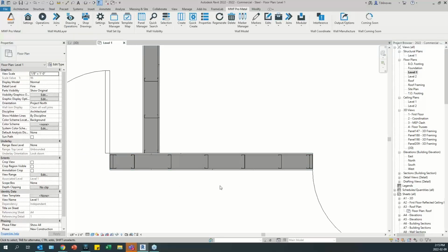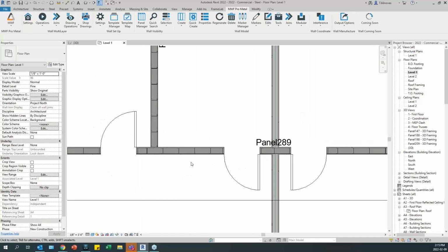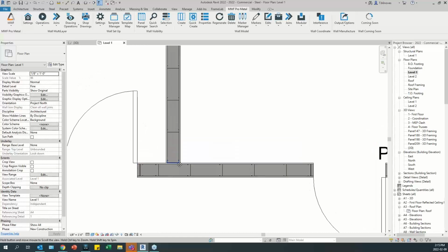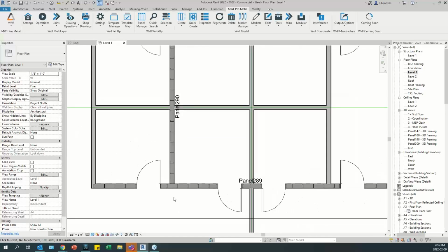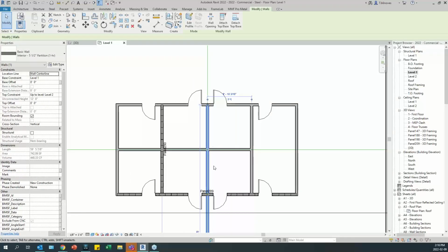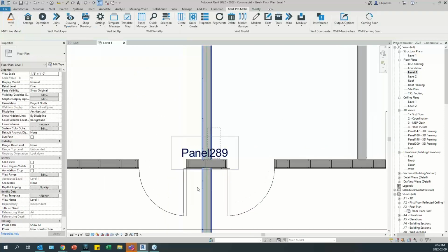Sometimes in the same project, you're going to have circumstances where you're not going to apply a join. You're just going to disallow and disjoin the walls. And in other places, you will use the joins. Okay, so you can choose whatever you think is best for your workflow and for your specific project. So for example, we could do this here as well. As you can see, we have a big wall. Again, the same issue will happen here.